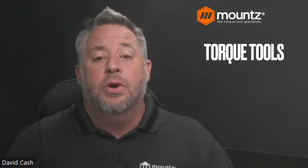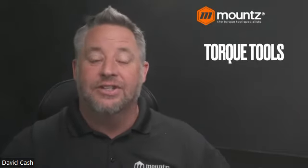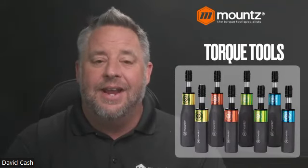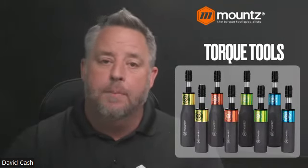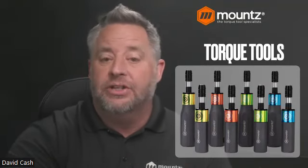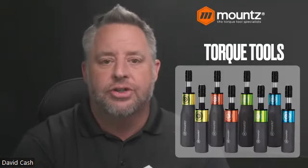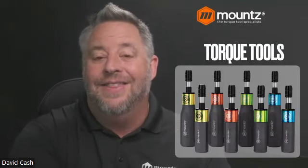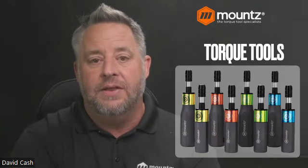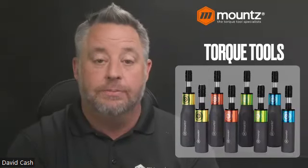Now, when we're looking at torque tools and the different styles of tool, if we look at a torque screwdriver, you simply turn the screwdriver, it reaches a certain amount of force, and then the screwdriver will simply slip, and that is the amount of torque that was generated on that particular fastener.